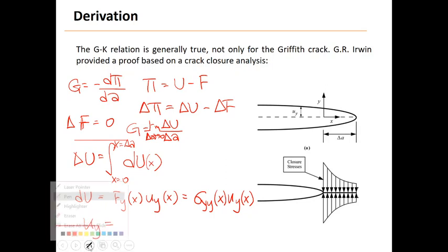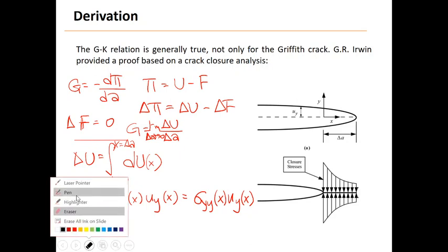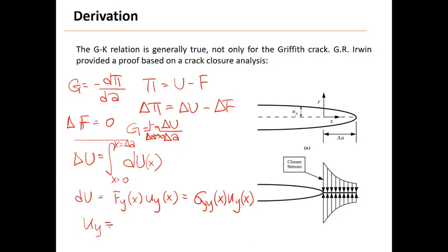We have uy, and if we go back to the displacement of a mode 1 crack and look at theta equals 0, because we're looking at the line in front of the crack, you just pick out that solution.